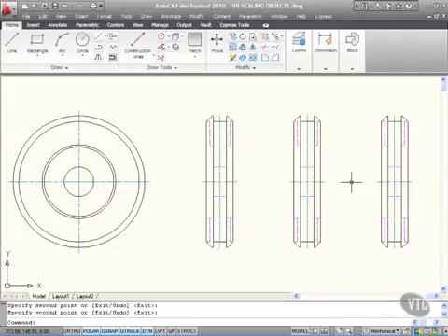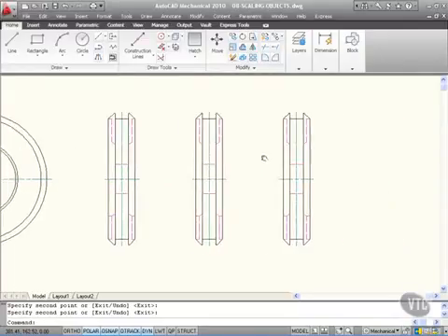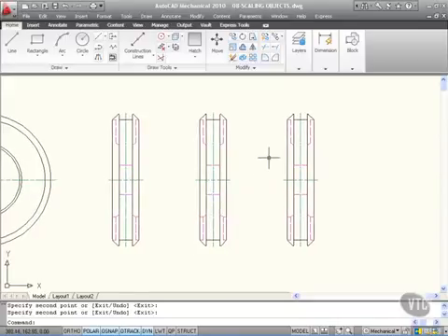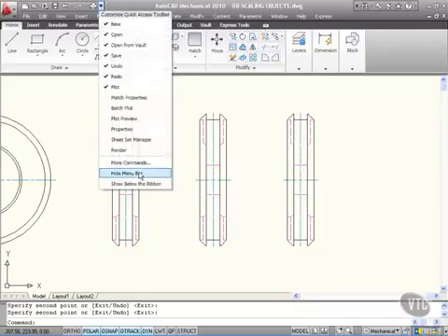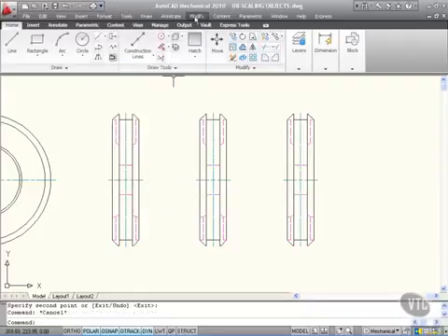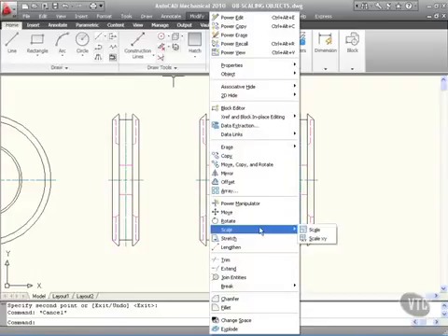I'm going to show you now how to scale in the X and Y directions separately. This is a specific AutoCAD Mechanical command. So I'm panning across a bit, get those central, like so. This one I'm going to scale in the Y direction only. So it's going to go vertical on me. Okay? So make sure you've got your menu bar. Click on the quick access toolbar, and click on show menu bar if you haven't done so already. And then we go to modify, scale, scale X, Y.